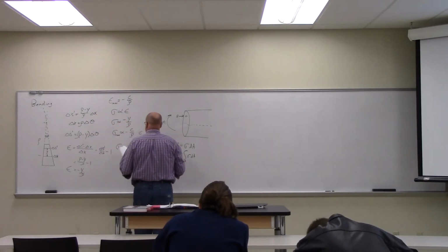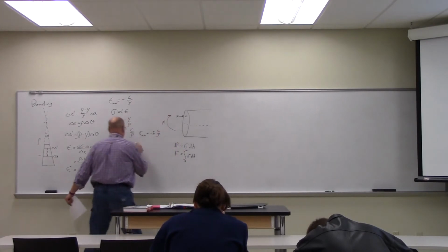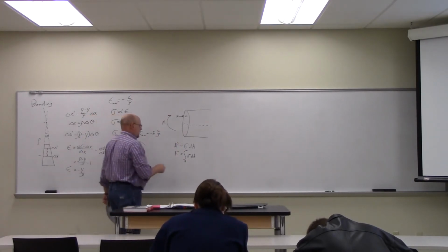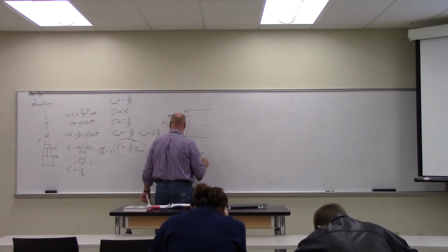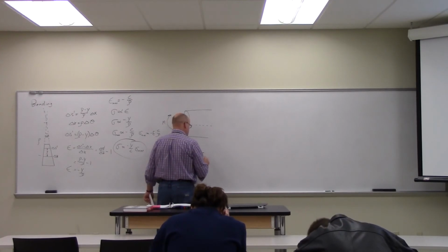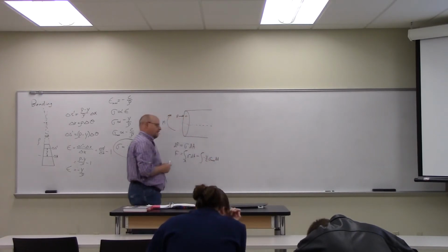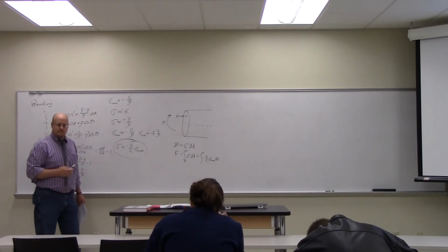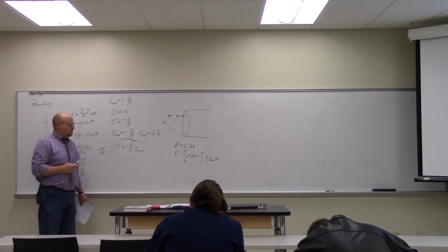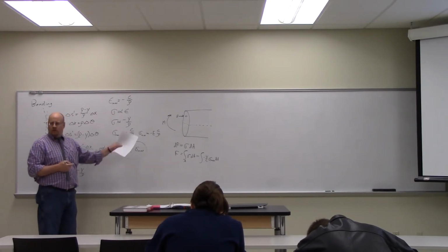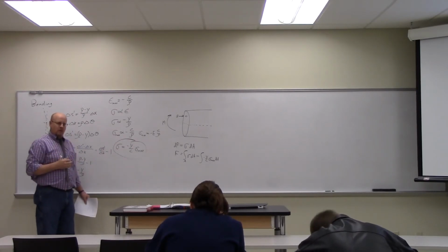Okay, well, we have an expression for sigma, right here. Plug that in, that's the integral of minus y over c times sigma max dA. Sigma max is constant for all points on the surface, so it comes out.